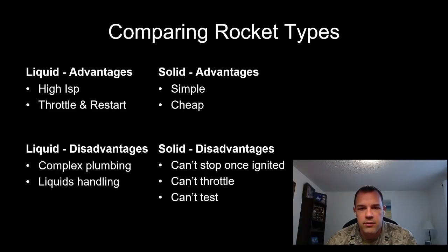So over to solids, they're simple and they're usually cheap. Once you pour up that compound and you have a solid propellant, it's not too difficult to get that thing going. Once it's going, it's just going about its way at full thrust until the propellant's all burned up. Usually a lot cheaper. You're not dealing with extremely tight tolerances in the turbo machinery, and you don't have to. You essentially just have the solid propellant in a nozzle.